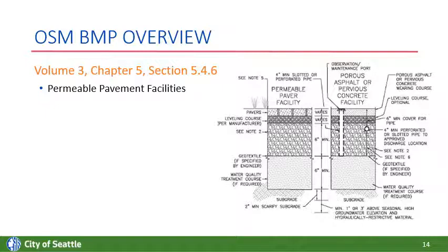For permeable pavement facilities, the design criteria for flow entrance, pre-settling, wearing course, subsurface check dams, geotextiles, and observation and maintenance ports have been updated. So as you can see, the detail has also been updated with the observation and maintenance port being shown there. The peak control standard sizing factors have been updated. The figures have been updated. Minimum construction requirements.